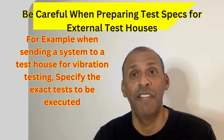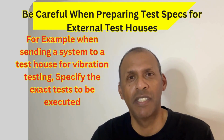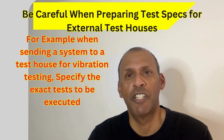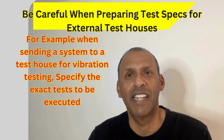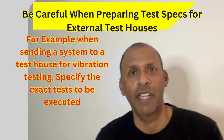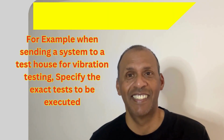For example, if your requirement is the equipment shall be compliant with the vibration requirements detailed in method 514 of MIL Standard 810, that's not enough to define the test specification. Ensure you go through in detail through the standard and ensure the specific tests applicable to your project are specified in your test spec, so that time and money are not wasted on unnecessary testing.